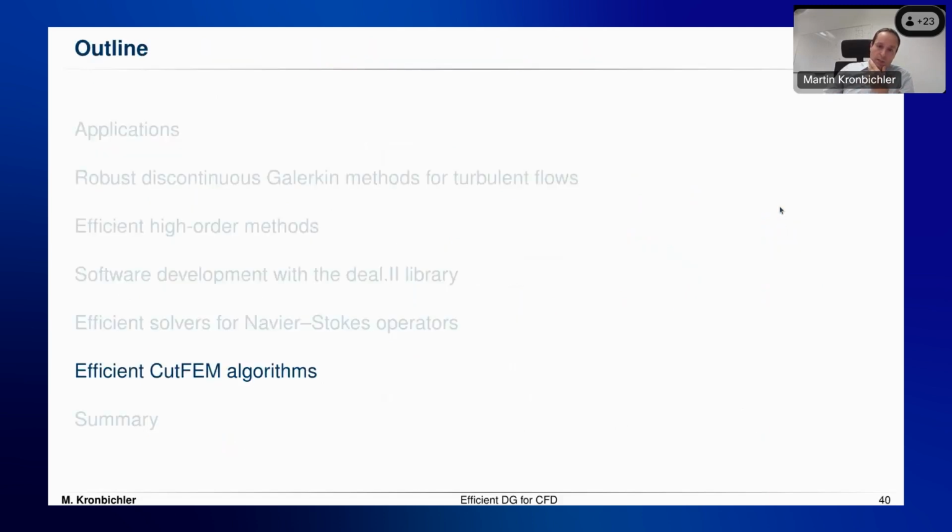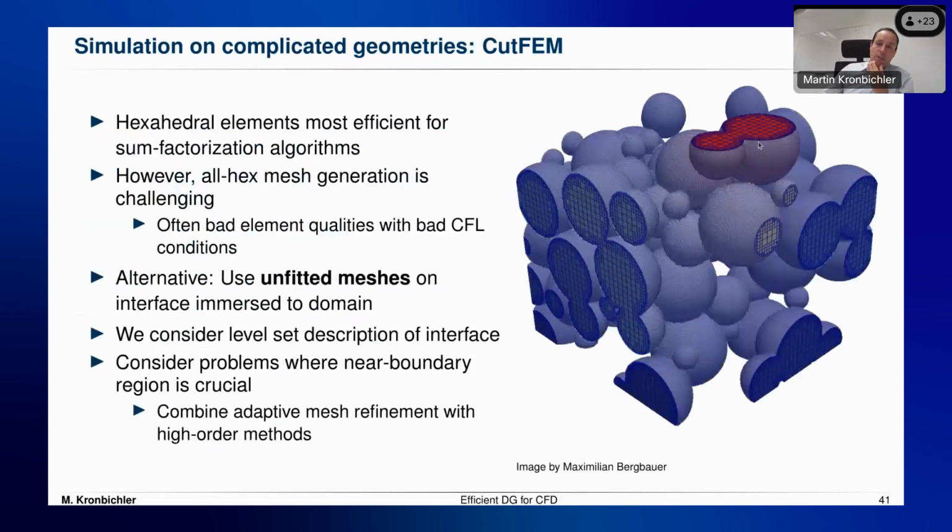And to conclude, I just have a few slides on the last topic that we worked on in our group here, which is cut finite element algorithms. I think when I told you that we use hex meshes because we like the performance, I should have said that meshing is complicated with hex meshes. And one of the directions that we're investigating, besides the fitted meshes, is also unfitted meshes. So unfitted meshes just use some level set function maybe.